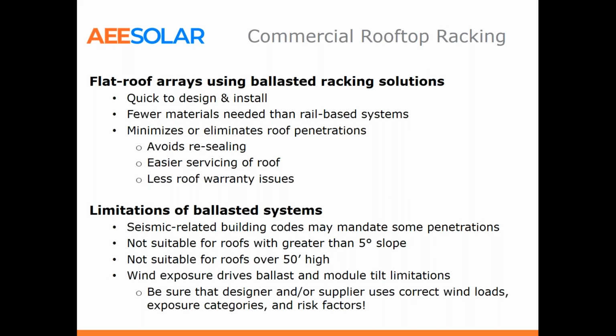The wind exposure definitely drives the ballast and the module tilt limitations, and be sure that your designer and/or supplier uses the correct wind loads, exposure categories, and risk factors. We do see a lot of people going to competitive system sites, doing their own calculations, not putting in the right wind speed or building height or exposure, coming up with a solution, and then coming to us and saying, hey, we want a competitive quote. And we come back and say, here you go. And they're like, well, why do you use all this material? Why is the ballasting so high here? Why is this more expensive?